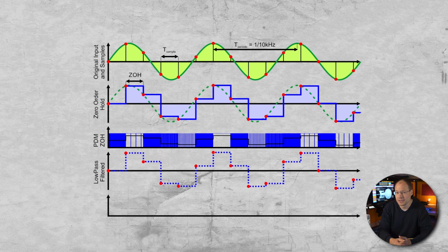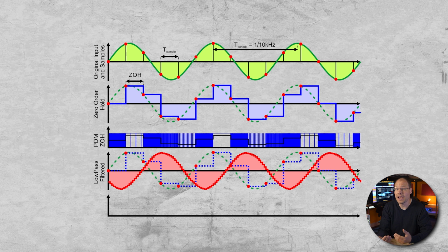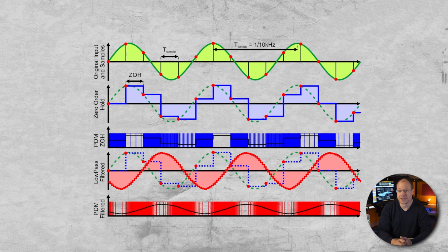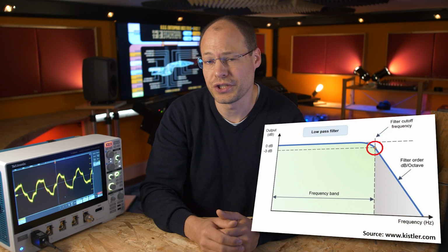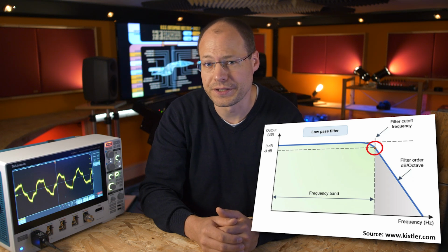To solve this problem, we can use a steep low-pass filter with the sample rate of the PDM modulator to achieve better results, as sharp edges can only be represented by high-frequency parts. To do this, we again use an IIR filter to cut off everything above the maximum usable frequency. With a sample rate of 48 kHz, the Nyquist frequency is 24 kHz. So we can place the filter somewhere around 28 kHz, remembering that there is a 3 dB attenuation at the designed frequency of the filter.